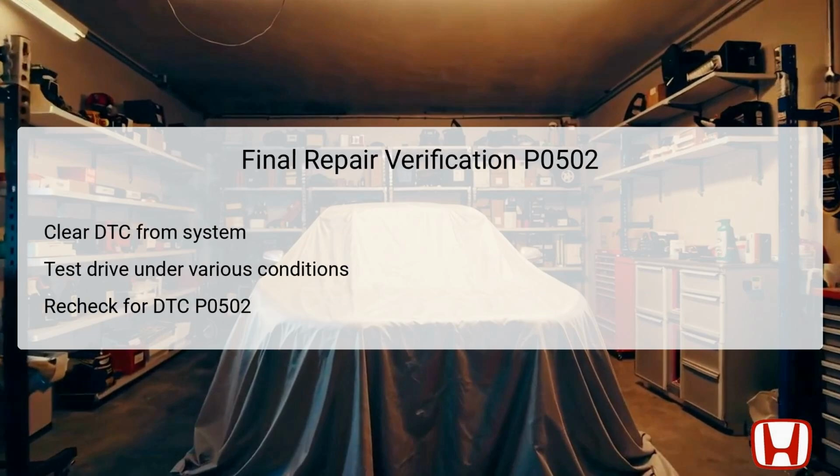After repairs have been completed, it is essential to clear the DTC from the vehicle's system to reset the onboard diagnostic memory. Following this, a comprehensive test drive should be conducted, simulating various driving conditions to ensure that the problem has been resolved and normal operation has been restored.